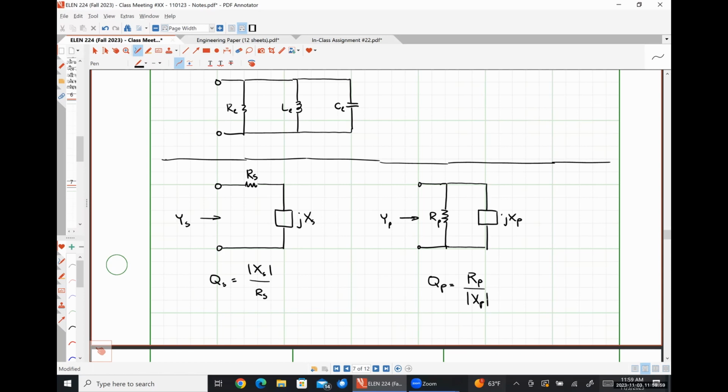Just as a quick aside here and to help you guys think about things, what do you think the resonant frequency of this series thing is going to be? Whatever frequency makes JXS look like 0, right? So if XS represented an inductance, we would have R over L, or negative R over L, right? It's just a first order circuit now. If it were a capacitance, we would have RC. Same thing over here. Simple stuff you guys have done before, way back in circuits 1.